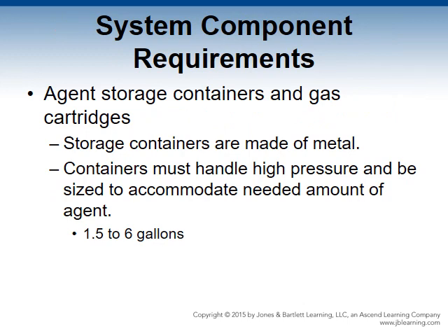Agent storage containers and gas cartridges. Storage containers must be made of metal that will not react with the agent. The containers must be able to handle high pressures. They must be sized to accommodate the amount of agent needed. The capacity ranges from 1.5 to 6 gallons.